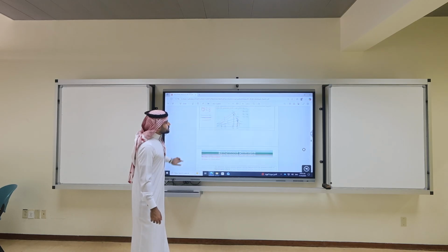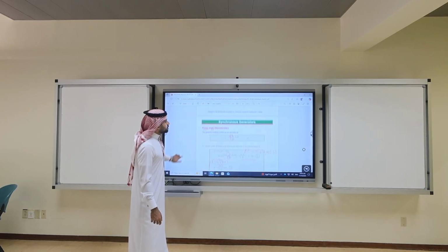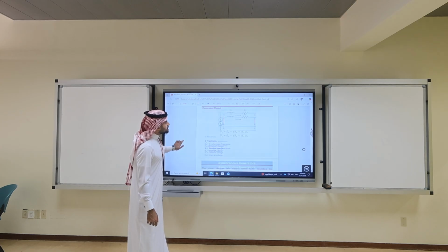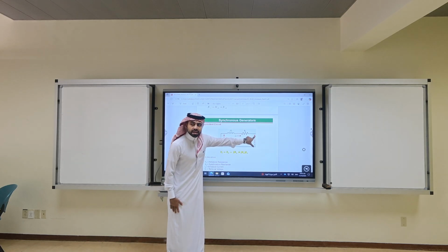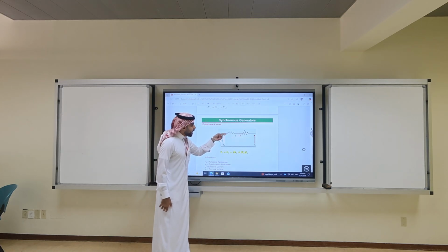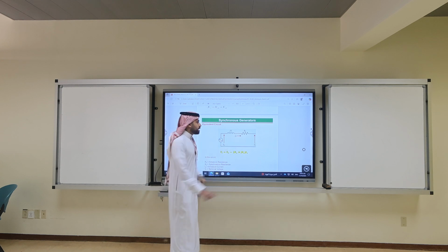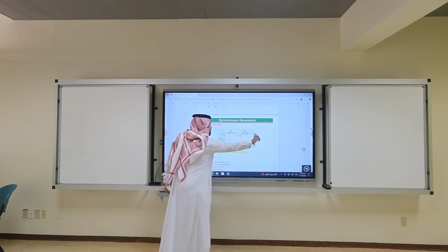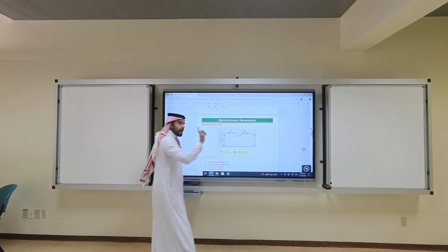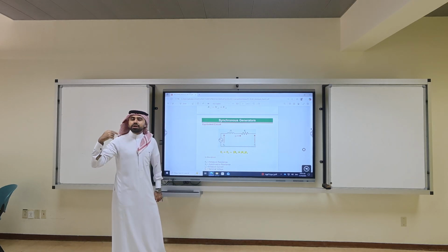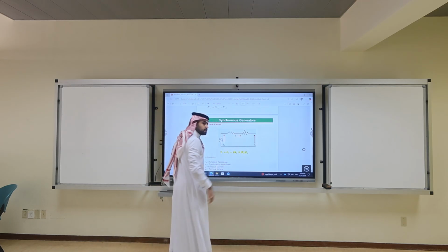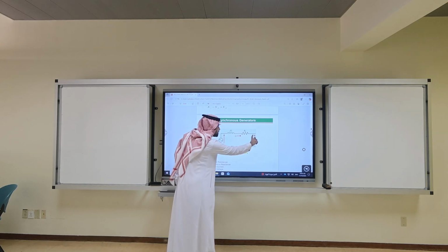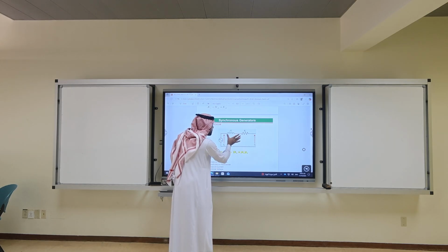Going back to the original circuit of my system, what I notice is that if I have no load, then this is an open circuit. If this is an open circuit, IA will be 0. If IA is 0, what is V at no load? EA. Let's say I connect some load, maybe rated load. What will be the current? Rated current. So VT will equal EA minus IA times (RA plus jXS).